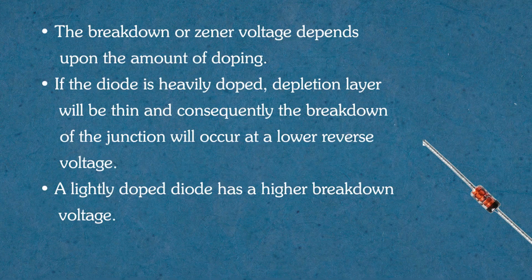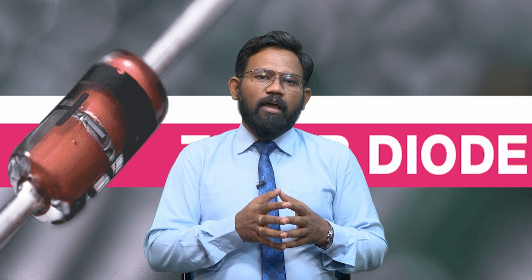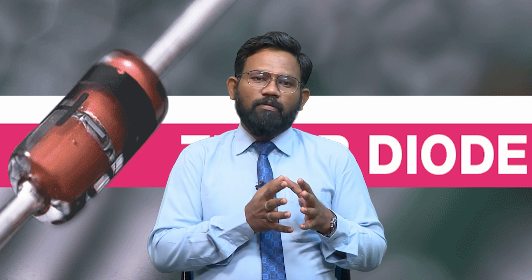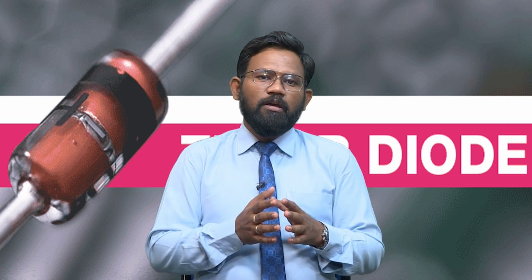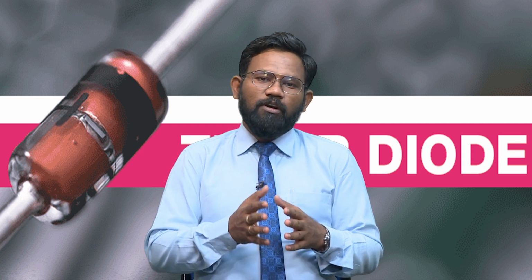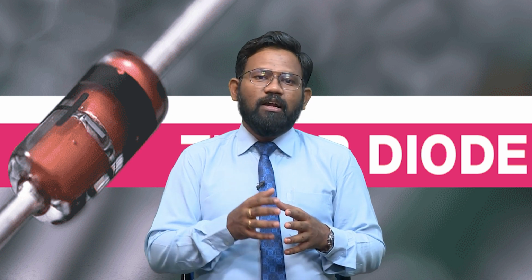So a lightly doped diode has a higher breakdown voltage. So if doping is increased, we can bring the breakdown voltage to a very small level. So it works in this fashion only. When a diode is heavily doped, its breakdown voltage is less, and when it is lightly doped, its breakdown voltage is more.